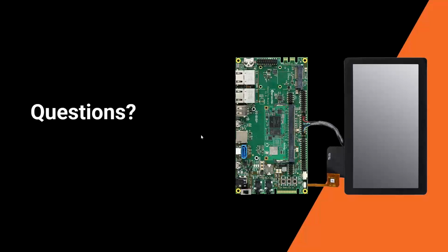And for i.MX 93, that is a 64-bit platform which has no GPU. Basically, you can just use the FrameBuffer backend. If you go through the wiki, you will see that at some point during the build, you need to set up which is the backend. By default, the available backends are always X11, Wayland, and FrameBuffer.